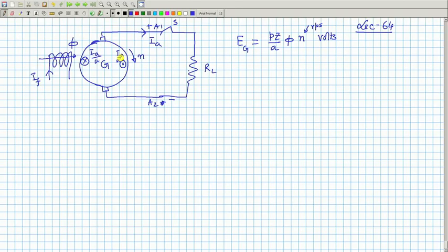And if they carry current in this direction, then by applying left hand rule, we observe that the electromagnetic torque will be in this direction. Direction of rotation is decided by the prime mover torque, T prime mover. And if these two are equal, then only the generator will run continuously at a constant RPM, delivering power. Any imbalance between Te and TPM will either accelerate or decelerate the generator, and this will happen when the machine is under transient conditions, and finally the machine will always seek to reach a state where Te will be equal to TPM.